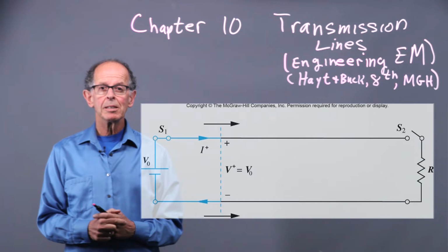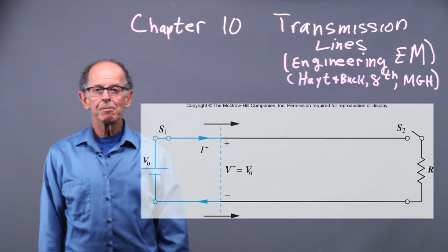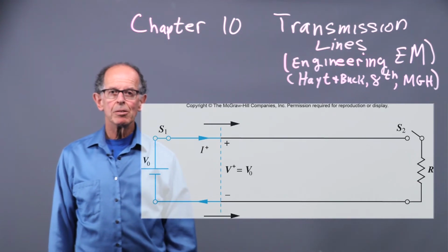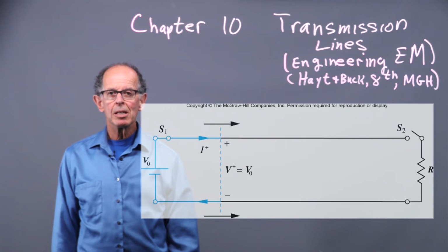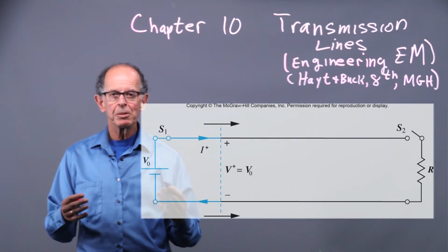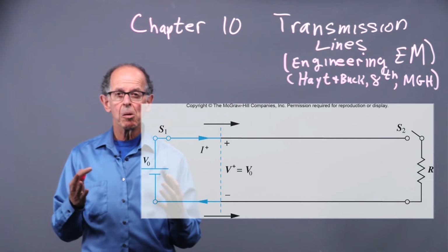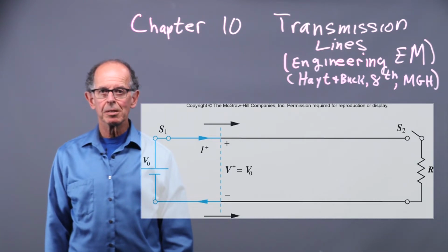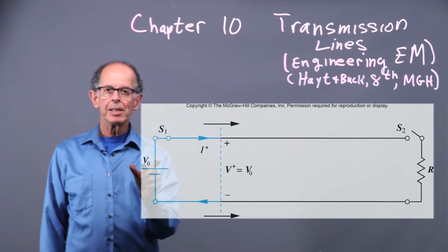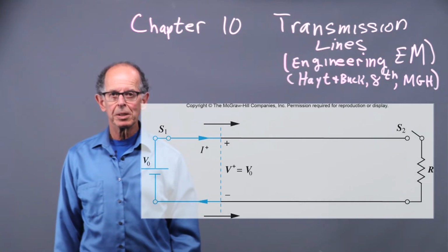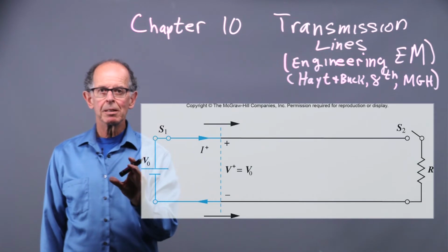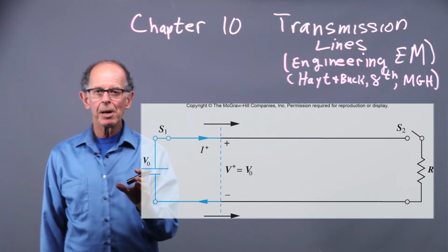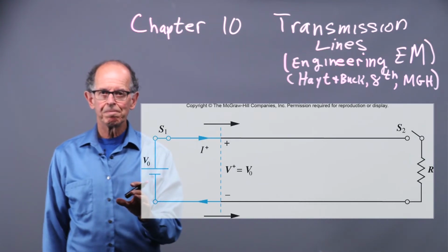And I want you to calculate the wavelength associated with the speed of light. So that's 3 times 10 to the 8th meters per second. And the frequency of, say, a typical lab frequency when you're doing test measurements on the oscilloscope, say 100 kilohertz, which is rather high. So what's the wavelength at 100 kilohertz? And then think about that wavelength relative to the size of the circuit that you're building. And that's the key point here in why we may or may not have to worry about waves. And we'll come back to that in class when we discuss it.